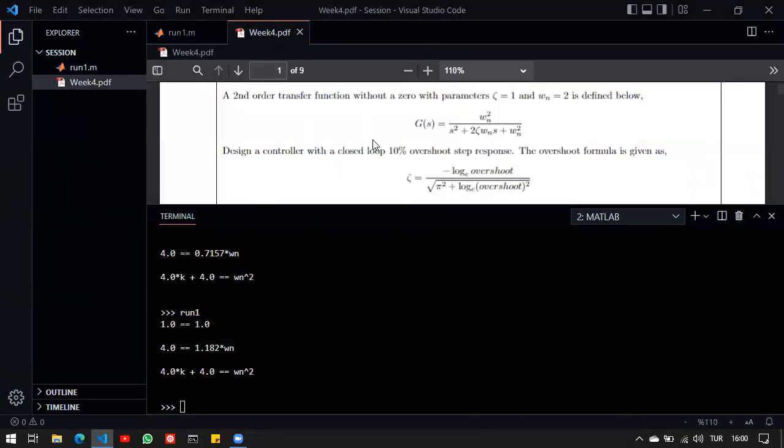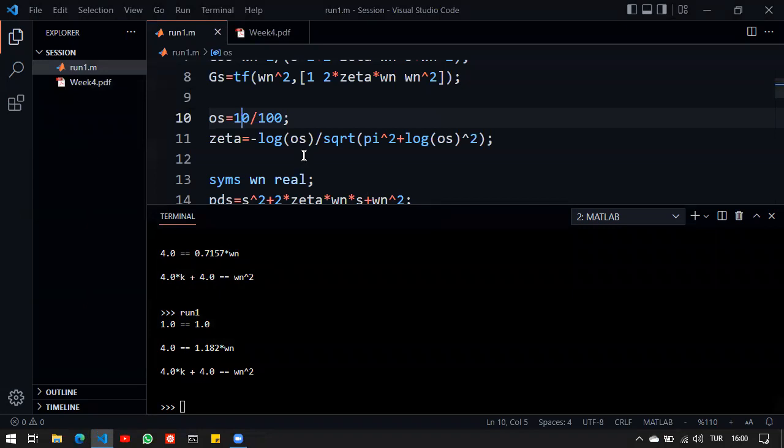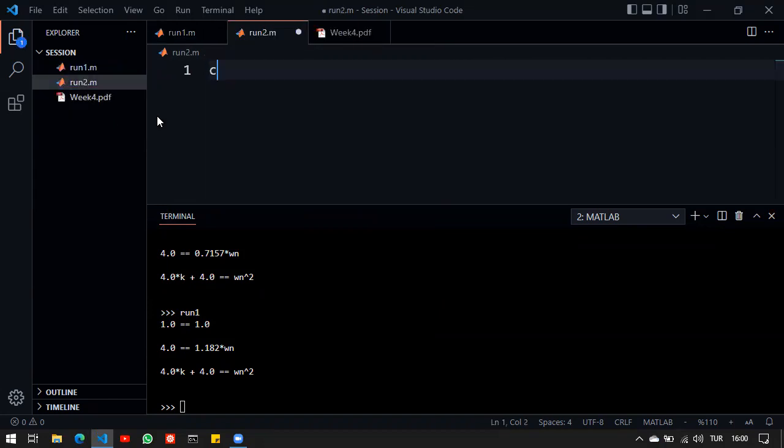So now, I've talked about this, and I've told you that, for example, in this case, I might go ahead and change my zeta value. So I can update my requirements. I can loosen them a little bit. That would offer me more solutions, hopefully. But another method is to update the controller or the structure of the controller. So a PD controller, for example, will be the example for that. So I might go ahead and choose a different controller, which can be a PD type controller.